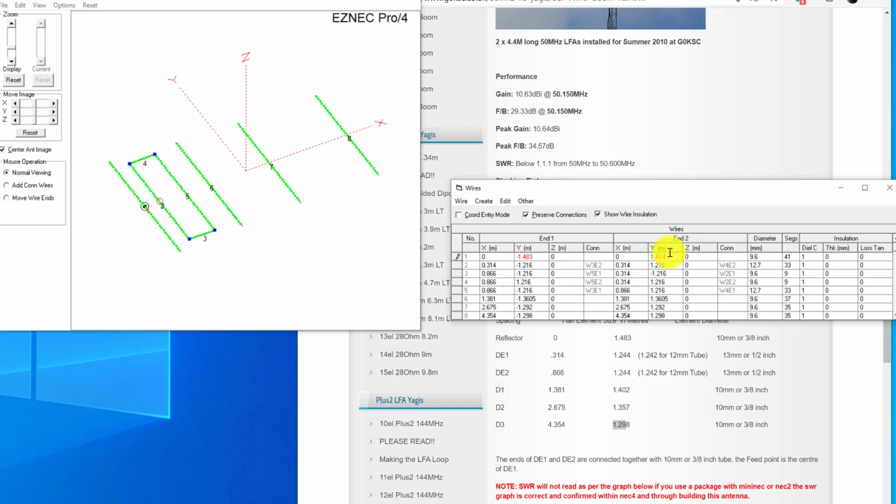and this is a generalization here, and it's not a golden rule as such, but generally the smaller the antenna, the bigger the reflector, and the smaller the last director. As you get longer in length, the rear element tends to be not quite as large, and the last element not quite as small. And once you get into multiple wavelengths, then it does change. But for up to sort of 9 elements or so, that's pretty much where it's at.